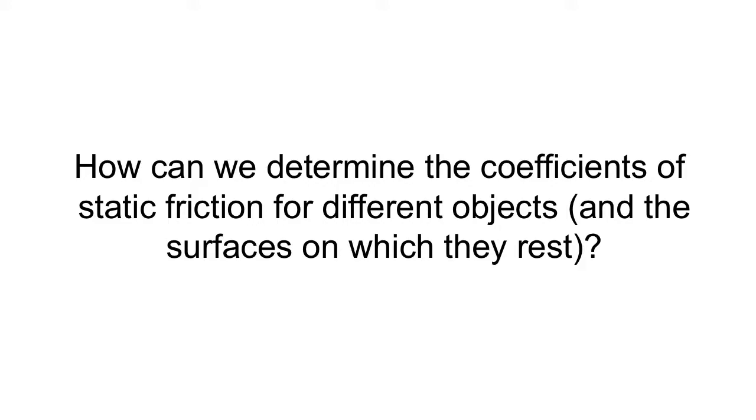If you notice, one thing that's kind of unintuitive is that mass doesn't matter in this problem. Mass and the g, little g, is embedded in this weight, but it's divided out. This often happens in these problems. Mass is not going to play a role in our static coefficient. And what I get just from trigonometry is that it's just the tangent of some angle. Okay? So now I have a way to think about how these measurements might work. I know that the static coefficient of friction is going to just be the tangent of the maximum angle that it takes for that block to begin sliding.